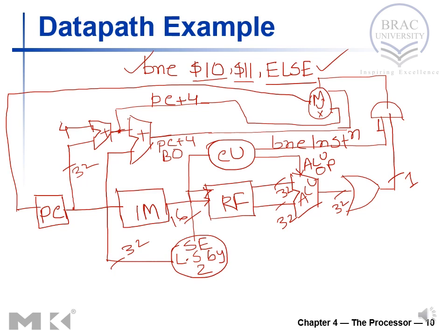So let's say this is port 1 and this one is port 0 of the multiplexer. Now since this is a branch instruction, the control unit would send the branch enable control signal. So through this link, control unit will send 1.